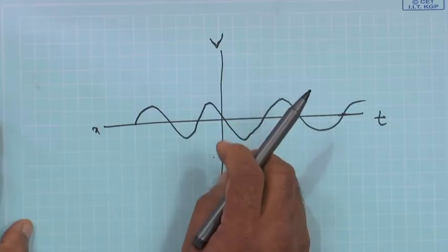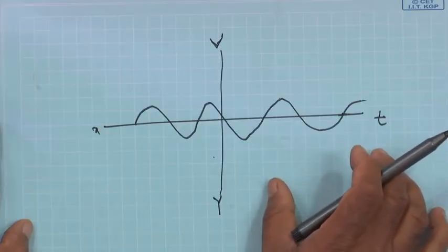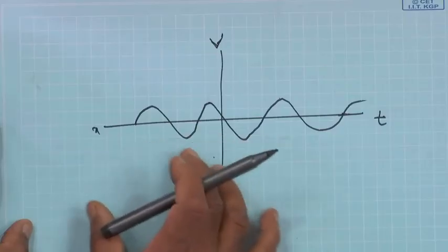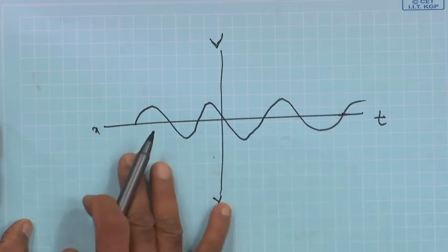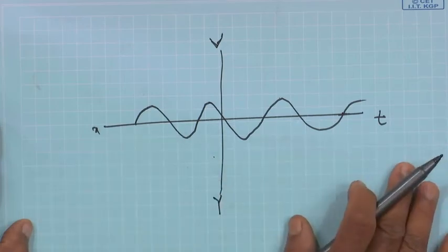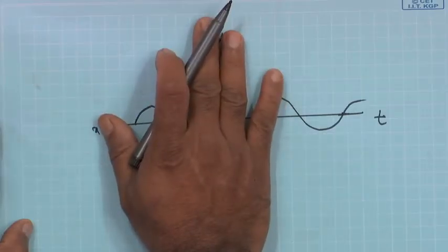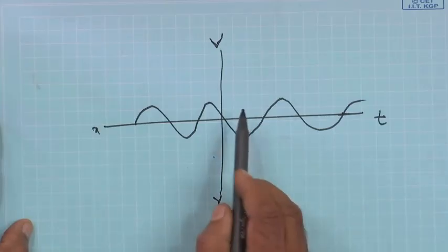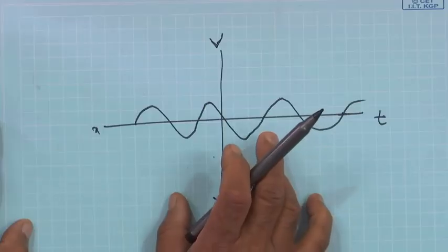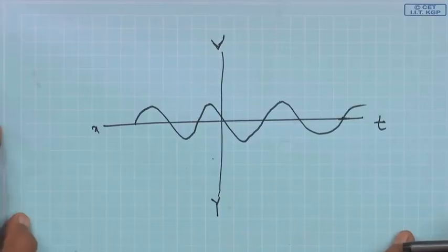And there is a calibration, time per division and volt per division, as I showed you, that is written: volt per division, time per division. For the horizontal case, it is time per division. For the vertical case, y axis, it is volt per division. So that calibration is there, or one has to calibrate; we can also recalibrate.